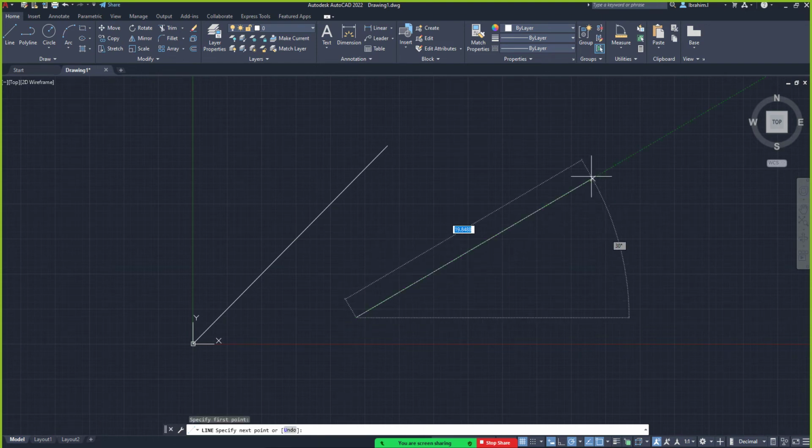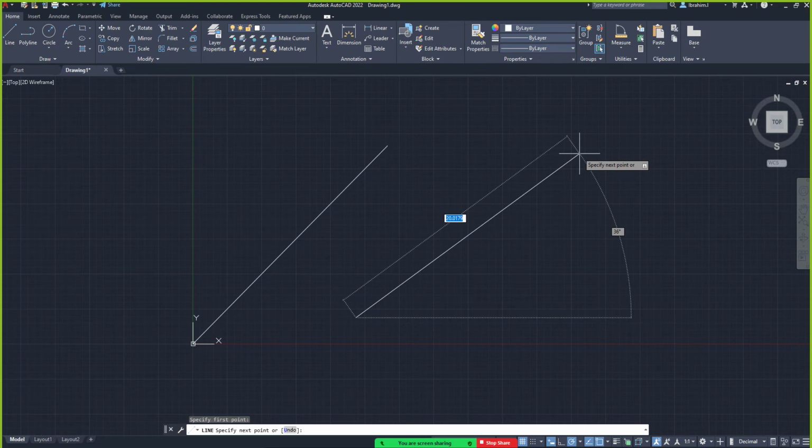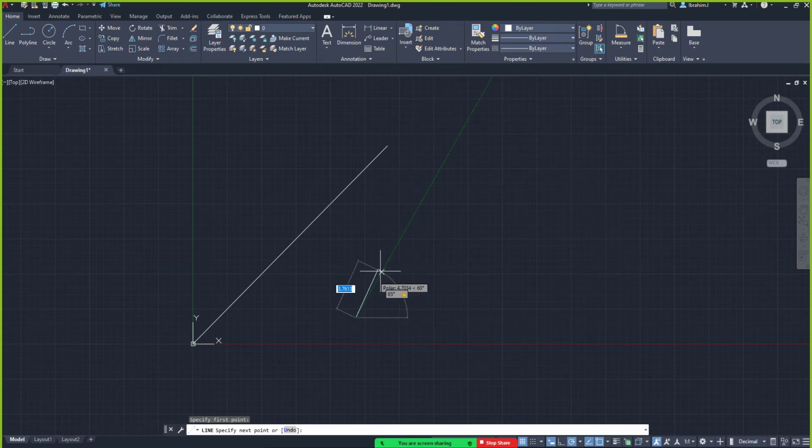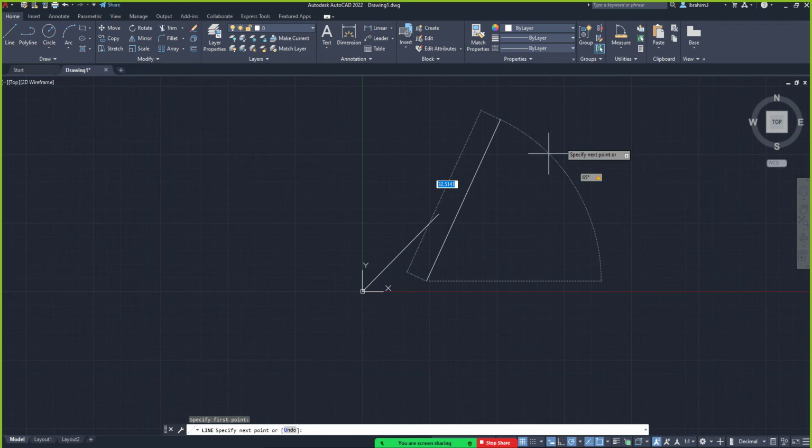I'm starting a line command there, and then you see immediately I click to specify my first point, I have two options. First, the blue option, you can see that I have options to change my length. When I click on tab, I have the option to change my angle. I will change this angle to 65. After changing my angle to 65, I'll click on tab, back to the measurement. You can see now that the angle is locked. It's only the length that I can adjust now. Are you with me? Yes, so that's just the basic use of our line command.